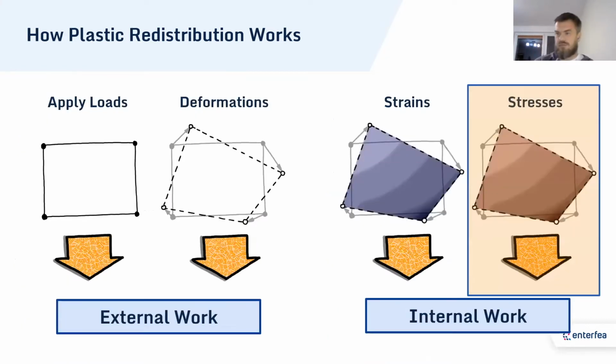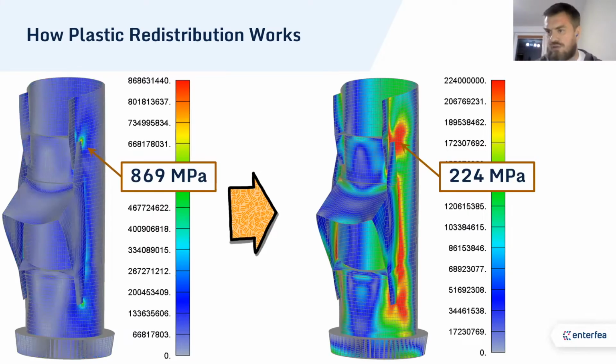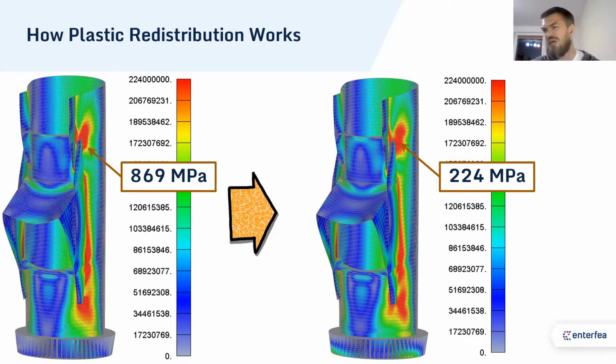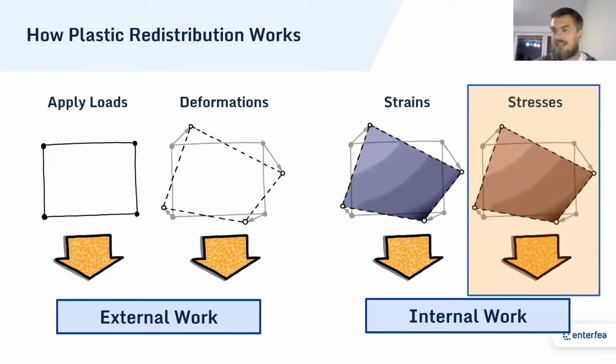Right? So the common conception, and this is what scares me mostly from the lectures that I do, would be, oh yeah, Lukasz just told us that we can ignore peak stresses, right? Think about it. I just showed you a model with 5,500 megapascals and it was okay. So the easiest conclusion would be, awesome, let's just ignore peak stress from linear analysis. We all know, as Lukasz said, that it will yield and redistribute, so that would be fine, right? But I explained to you how convergence works purely so I can use this argument.